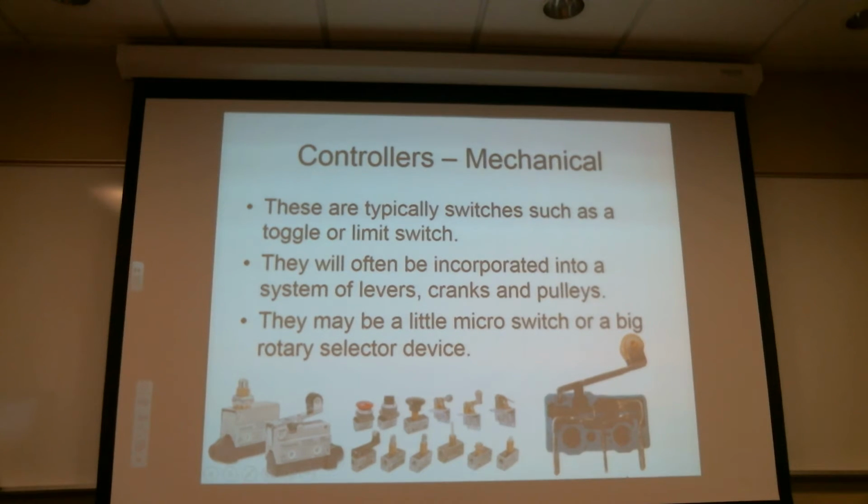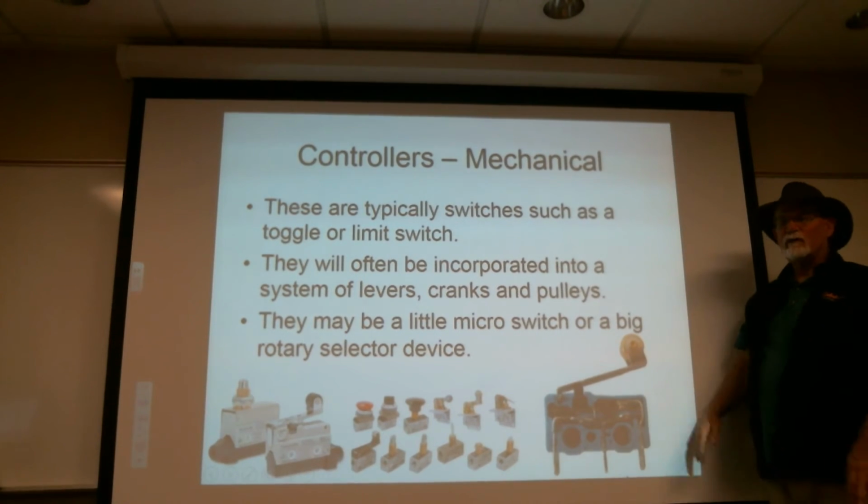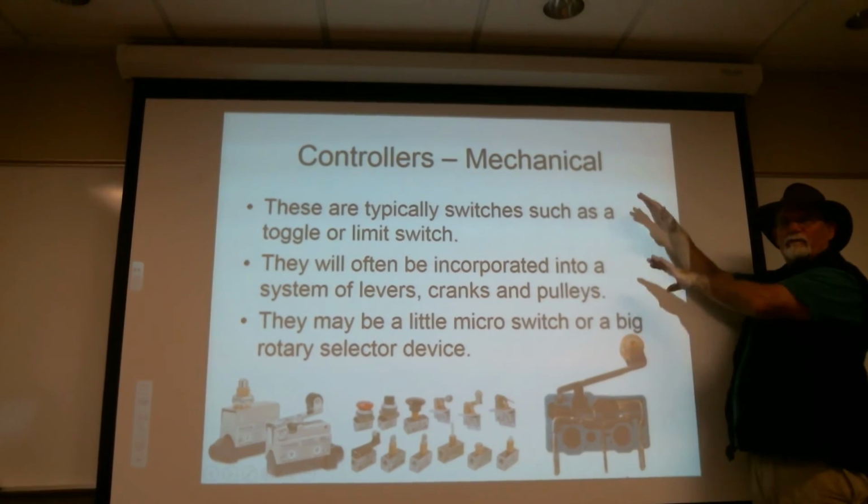It causes the motor to come on going down. So the motor goes down, and that plate starts moving because the cable's moving, and all of a sudden the limit switch comes to an open and the motor stops. Okay, I've now gone 10 degrees. 20 degrees. Come back up. In this particular case, the lever actually doesn't connect to any switches. All it's doing is upsetting a range of 2 switches for which the whole assembly will move as the flaps move.